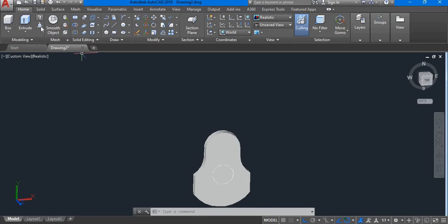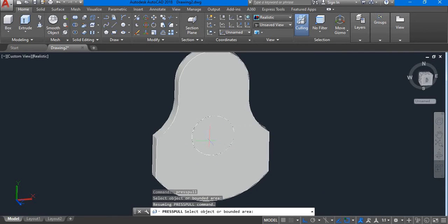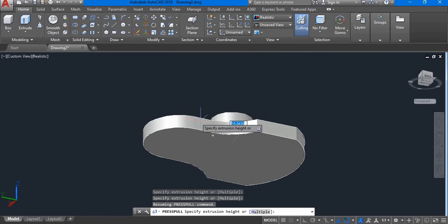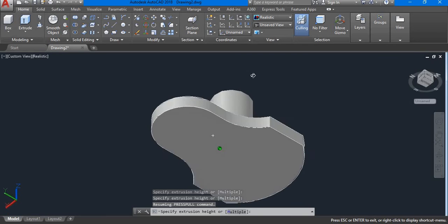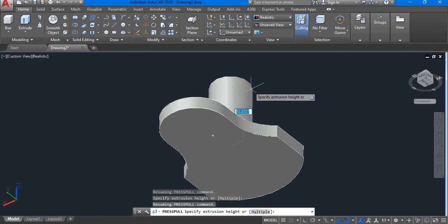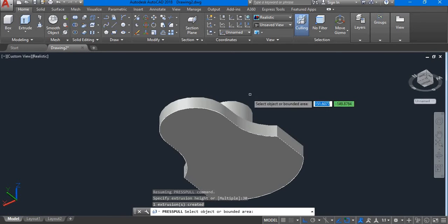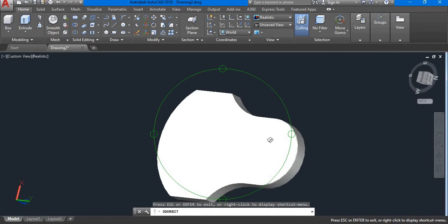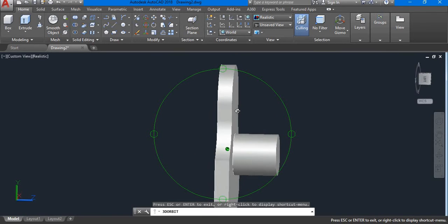The next thing we'll do is we press pull it, take it to the midpoint of this circle, let's click, bring it all out, and the length is 30. Just type in 30, enter, escape, and let's turn this so that we would see what we are drawing.